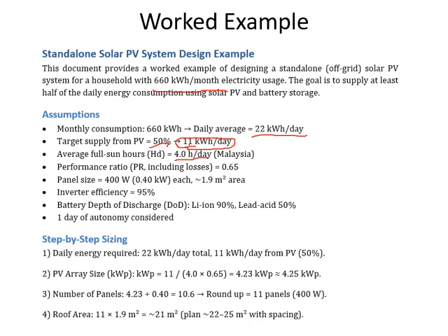So I'll need a battery first of all. And then for the standalone, the performance ratio is lower. For a grid connected, it can go up to 0.8 or something, because for standalone you have to set up the battery, and all this wiring will cause a drop in this PR value, performance ratio.